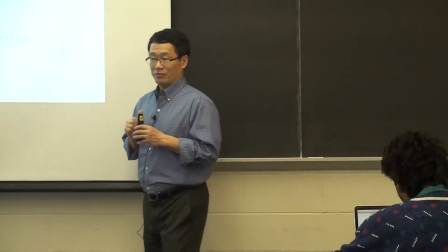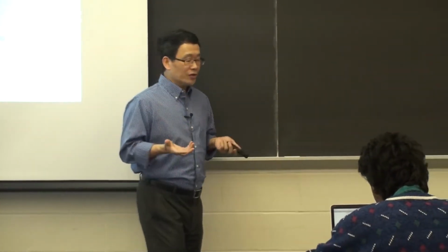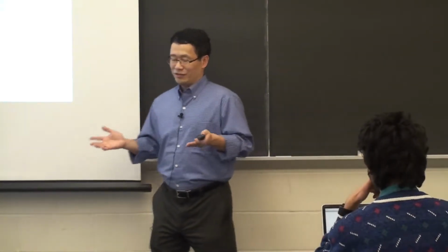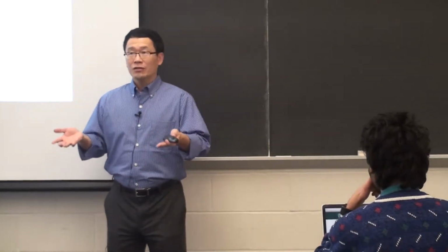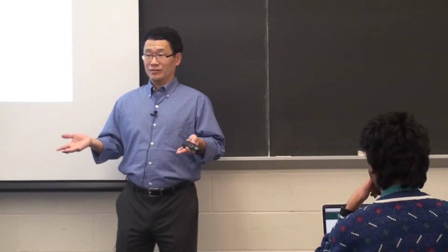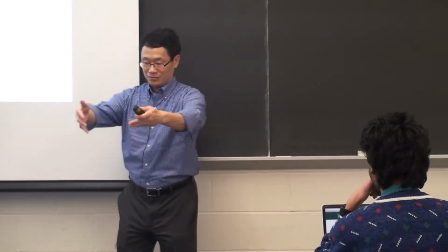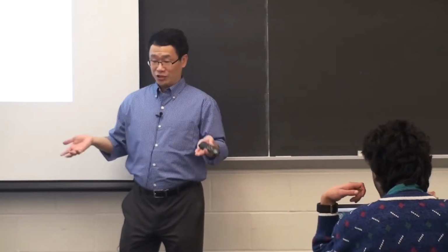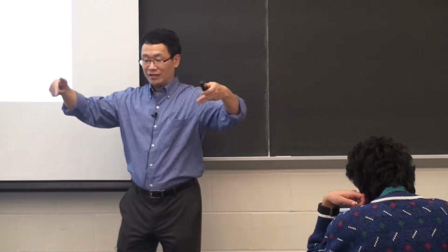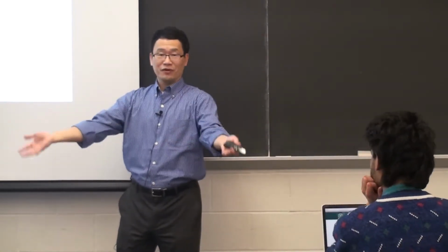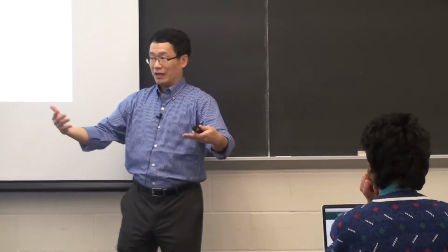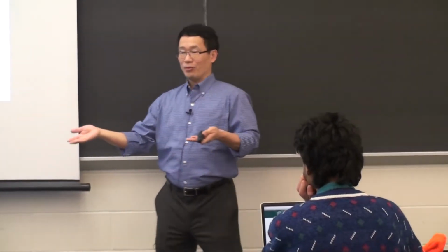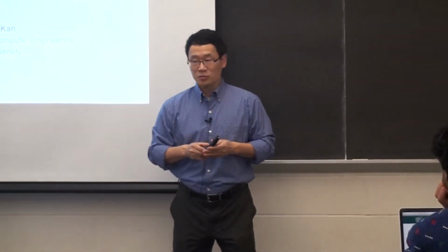Second is geometrical optimization. You know there's a shape, but you don't know what that shape is. There are two ways of looking at it. The first way is I don't know what that shape is, but I know the shape is smooth. If I make a boat, the boat needs to be in some shape. I don't know that shape, but I know if I make anything that's discontinuous, it will cause a lot of turbulence and be very difficult to sail. So I know it should be curved. Then what is the best curve to fit your problem? That comes with the idea of spline optimization.